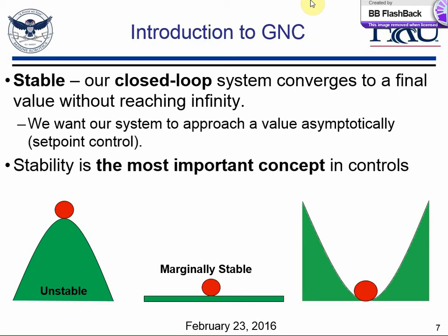Is it good or is it bad to have a marginally stable system? It depends. That's exactly it. Sometimes it's fine to have a marginally stable system, and sometimes it's very bad. Sometimes marginally stable systems will just go from one position to another and stay there, which is fine because it's not going to break anything. Or sometimes they will drive your system to oscillation. Those oscillations can cause damage to the machinery operating it, right?